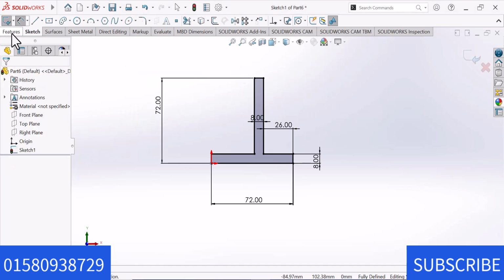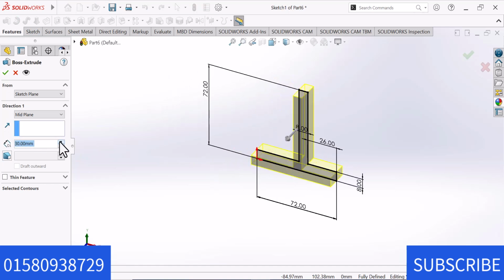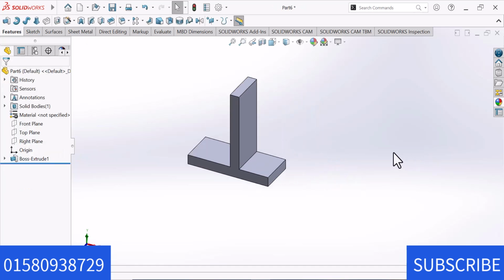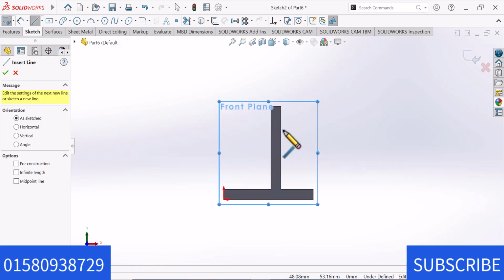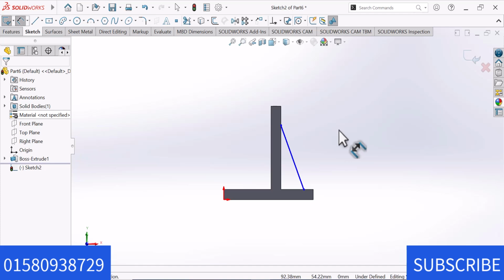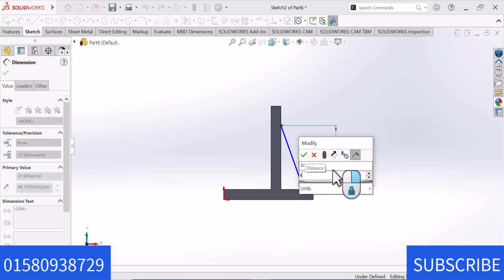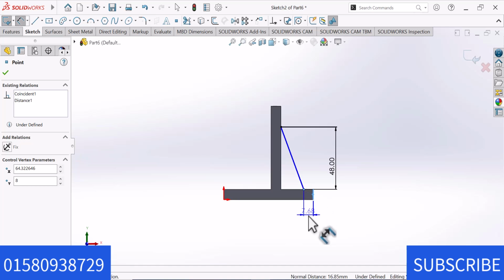Okay, now go to Feature and select Extrude. Now extrude 30 from mid plane. Okay, now go to front plane and sketch. Now draw the line here, select. Now this line dimension 48, and this point and this line dimension 8.